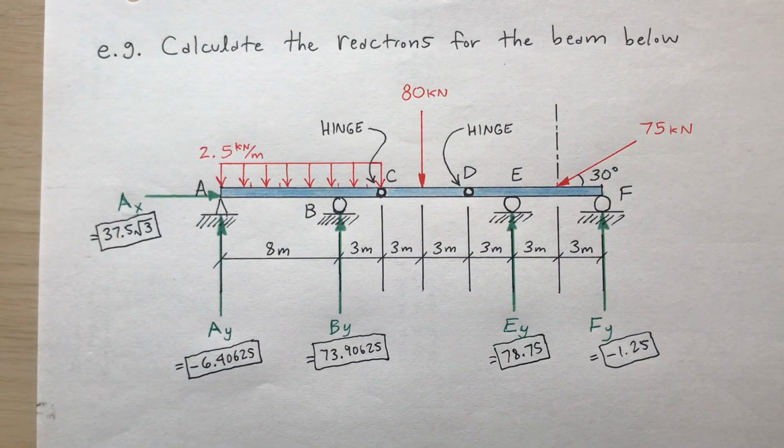So we would call those new equations equations of condition. The phrase equations of condition refer to additional equations in terms of loads and reactions. For example, the sum of the moments about hinges C or D. So an equation of condition would be, for example, the sum of the moments about point C. Another equation of condition would be the sum of the moments about point D.